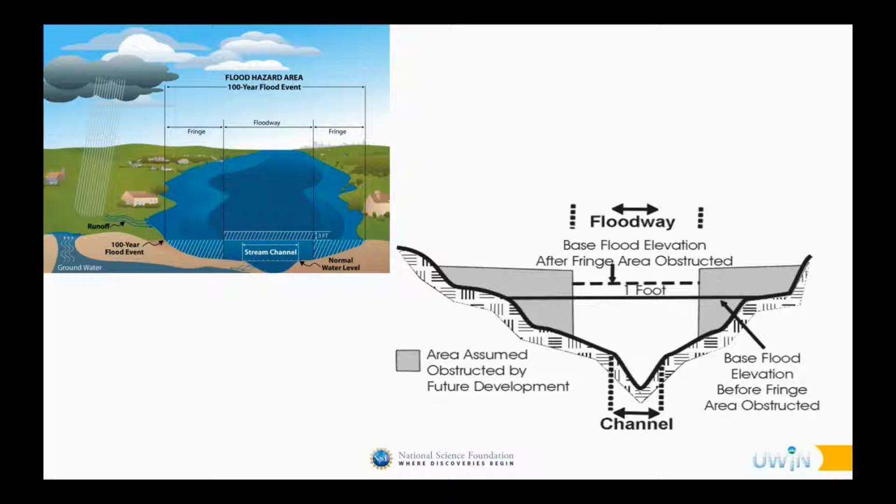There is some resolution within that floodplain in terms of distinguishing between a flood fringe and a floodway, in terms of what's allowed in terms of human activities in the floodplain, and we won't get into the details of how that's determined, but the bottom line is that you end up with a map that doesn't really represent the uncertainties in the edge of the floodplain. So it doesn't matter if the confidence bands around the edge of the floodplain are 10 meters wide or 1,000 meters wide, you still get the same line.